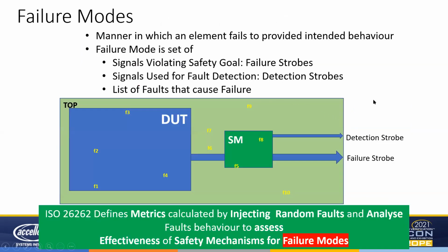So we know what the different kinds of faults are, and the fault classification that ISO 26262 recommends. It also recommends some methodology to follow. One of the first things in the methodology is to define your failure modes. So what are failure modes? This is defined as the manner in which an element fails in your design to provide the intended behavior.